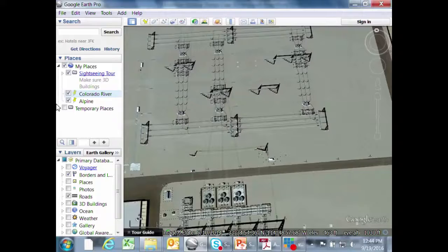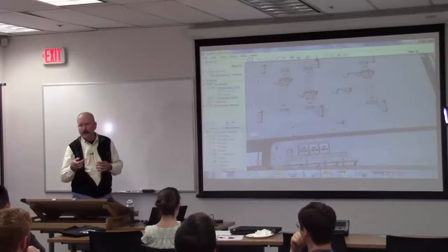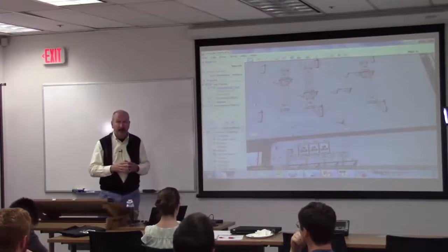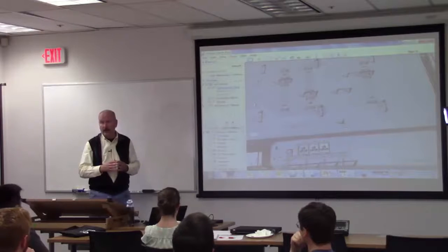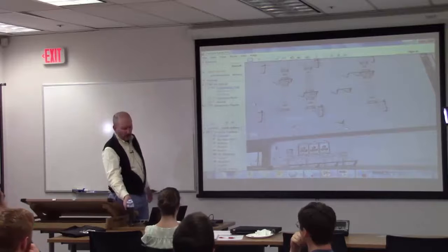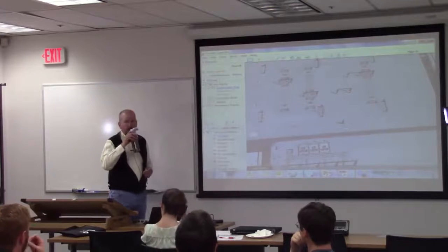Now, one other aspect, and then I'll leave this and we'll wrap up. Some people like to embed conduits in foundations and have the conduit come up right in the right spot so it goes right into the control cabinet. You'll probably see that in some of your designs. I recommend against that. It's just another thing to get screwed up on your project, whether we make the mistake or the people make the mistake out in the field. It's just a mistake waiting to happen.